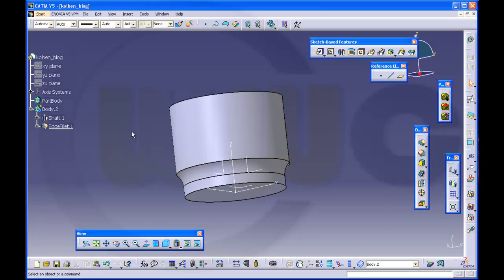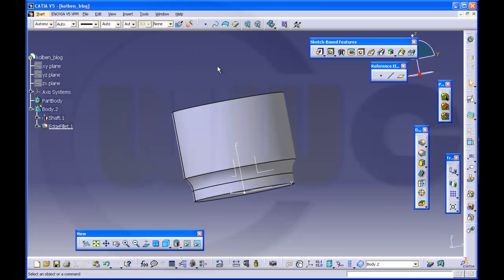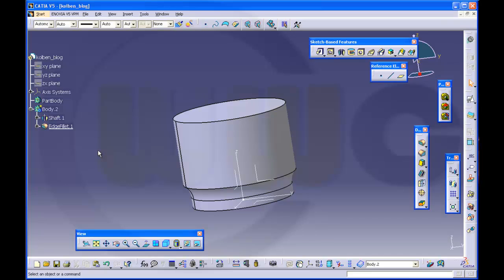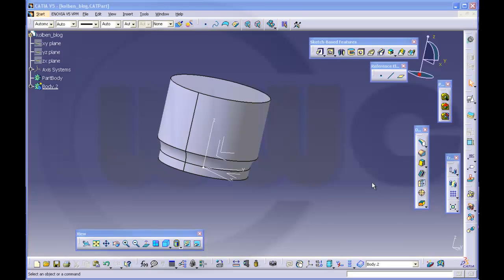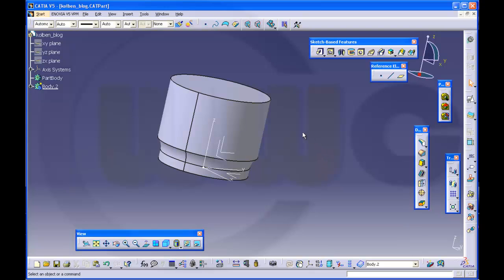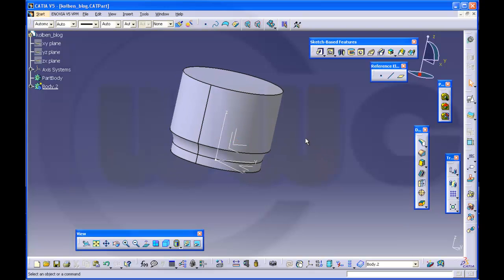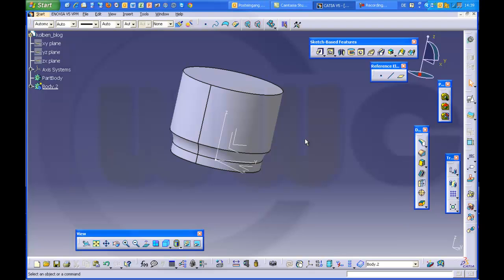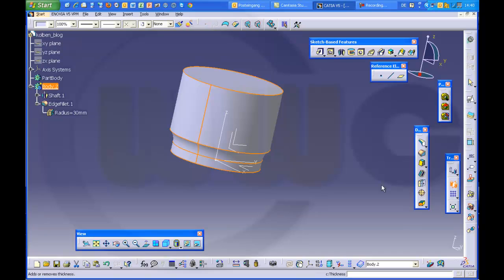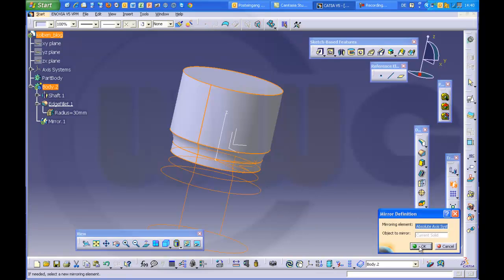First I want to make all the bodies for the volume and then I will make all the bodies which will remove volume. In this model I will do a whole lot of mirrors, because usually you can always mirror a body, but you might get problems if you try to mirror some features. So I will mirror this body on that plane.